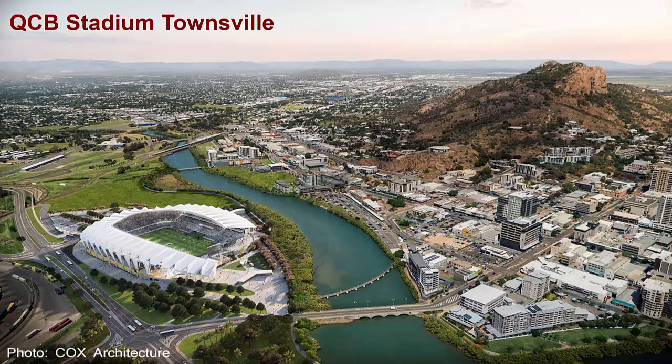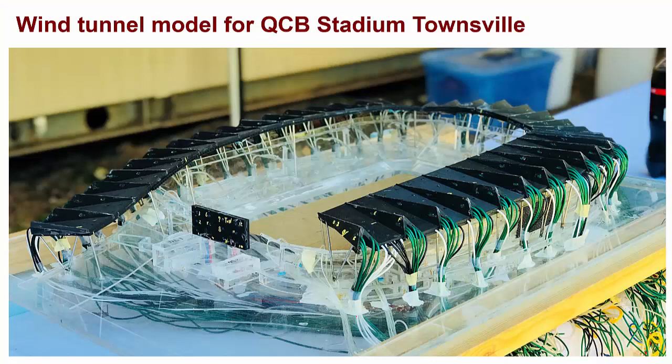To calculate the wind loading on the stadium roof, the JCU Cyclone Testing Station built a 3D model of the stadium and did testing in the wind tunnel to find out what wind pressures can act on the roof structures, and then used that to find the wind loading on the structure. So the structure was designed based on the data from the wind tunnel testing. And as a part of CS2003, you will be doing a practical in the wind tunnel and see how to find the wind pressures using the wind tunnel.